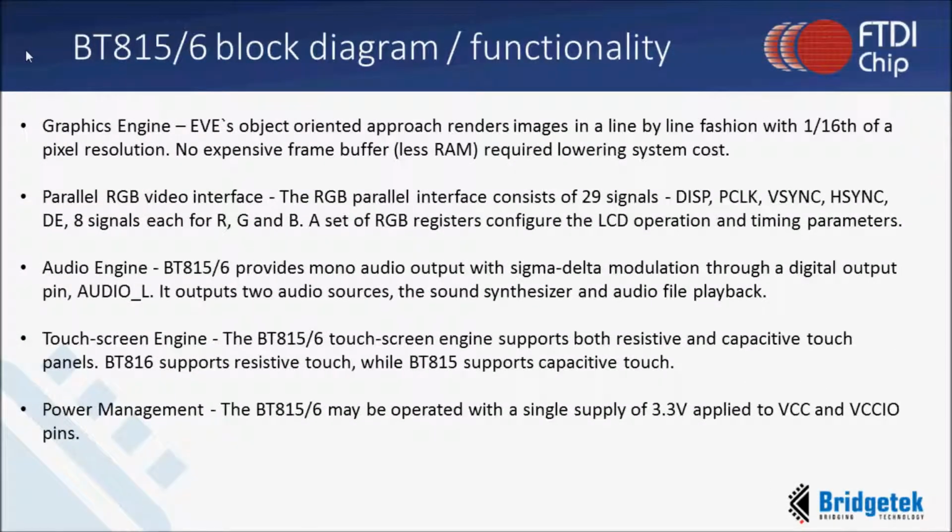Moving on, our graphics engine is the next functional block. Eve's object-oriented approach renders images in a line-by-line fashion with a 1/16 of a pixel resolution. This means no expensive frame buffer is required, lowering system cost. Next we have our parallel RGB video interface.